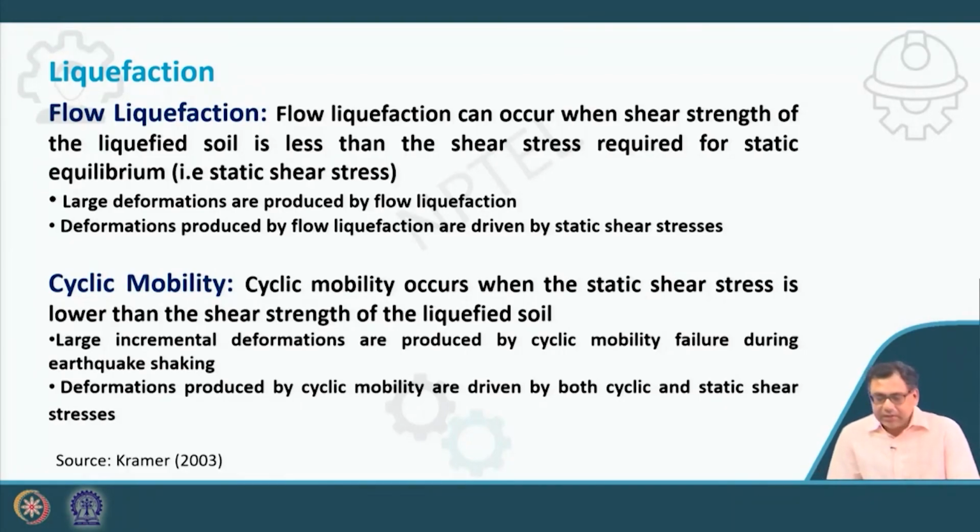Because here your shear strength is less than the static shear stress, the cyclic stress helps to reduce the shear strength of the soil, but the deformation that occurs in the case of flow liquefaction is due to the static shear stress. Clear? That means the reduction of strength is due to the cyclic loading, but the deformation produced by flow liquefaction is driven by the static shear stress.